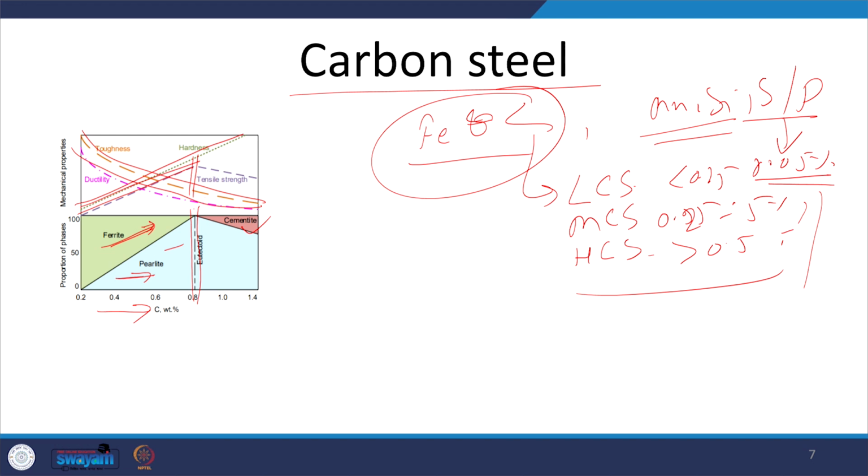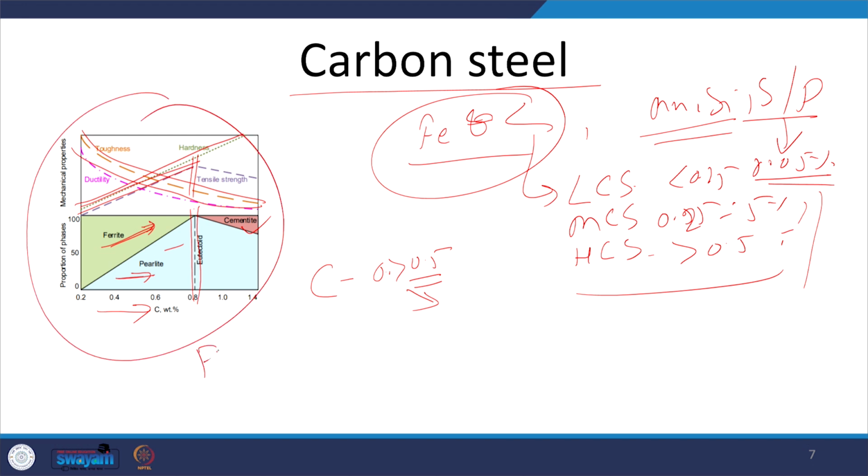Okay. So, this is about the properties. If the carbon content in steel is greater than 0.5, then what will happen? It will have a greater tendency during the welding. This corresponds to the iron carbon diagram, but when welding is done, increasing the carbon content increases the tendency of the formation of pearlite and martensite in the weld zone, even in autogenous welding, and that in turn increases the cracking tendency, hardening and embrittlement of the weld joint.